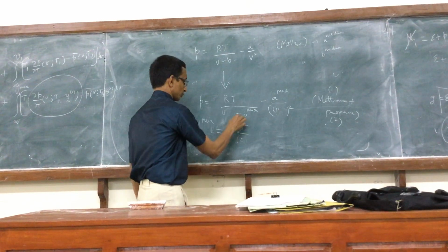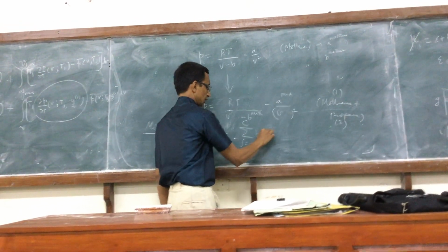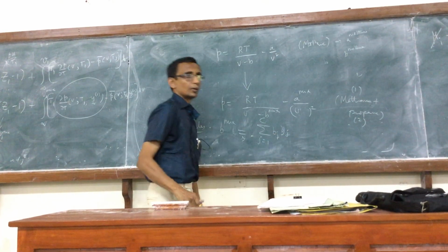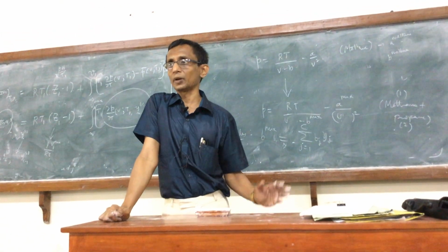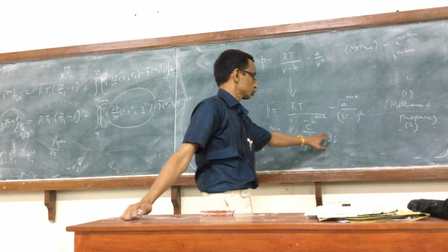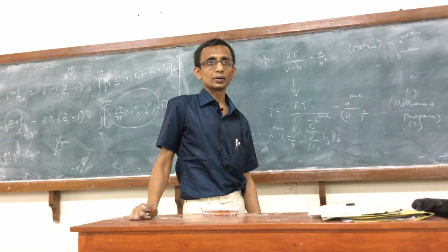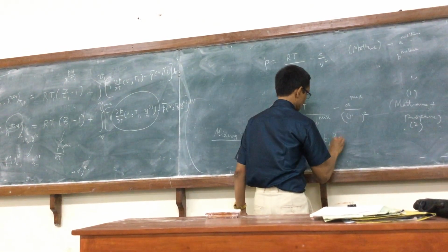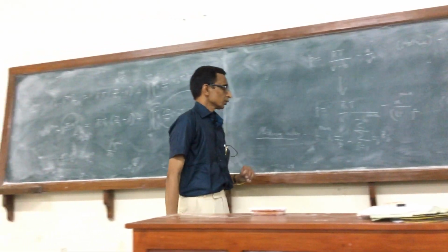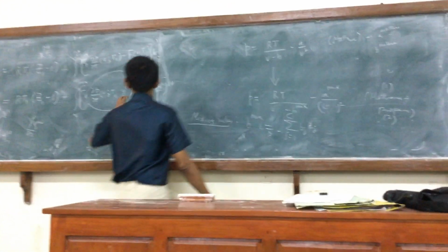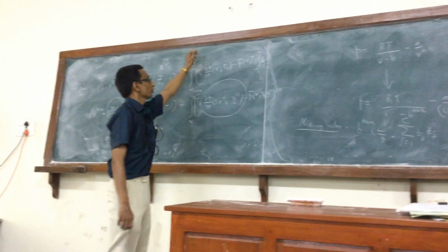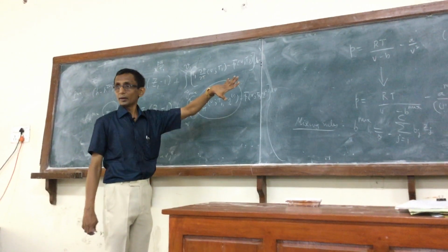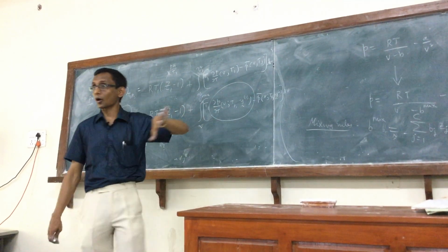In fact, I can even write it for C components. Bj, Zj, or if you want Yj. But it applies to any mixture, it can even apply to a liquid mixture. Then you choose the corresponding mole fraction of the component in the liquid phase, right? Bj, maybe let's make it very gentle. So now you can see how the dependence of the P on the mole fraction is coming in. It is coming through the parameters themselves. Now they are no longer constant.